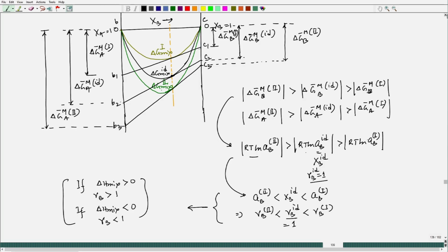And from here we can also see how those are related to the activity term now, because there it was simple, as we did not have to consider the activity coefficient gamma value. We expressed everything in terms of x A, x B, but while talking about equilibrium between phases considering non-ideal cases, we cannot do it with respect to composition or mole fraction; rather we have to consider the activity term.